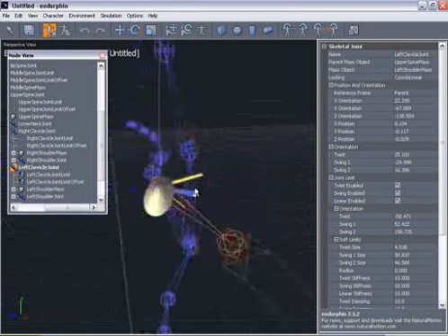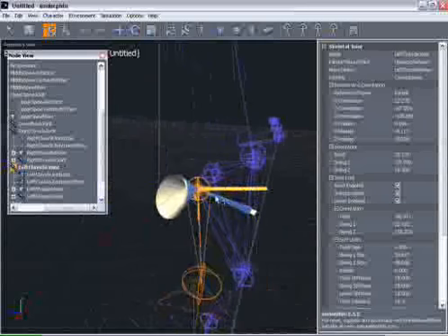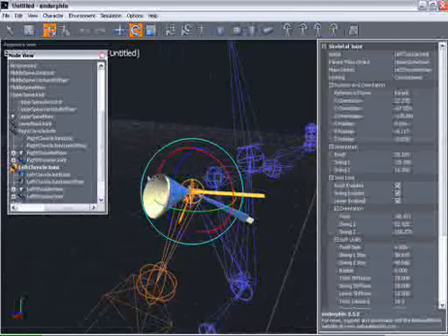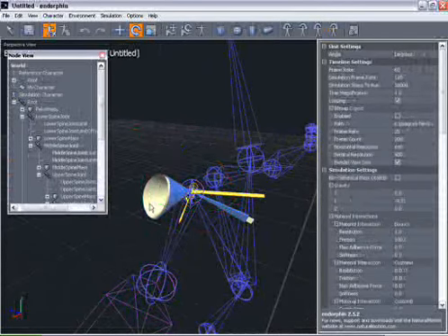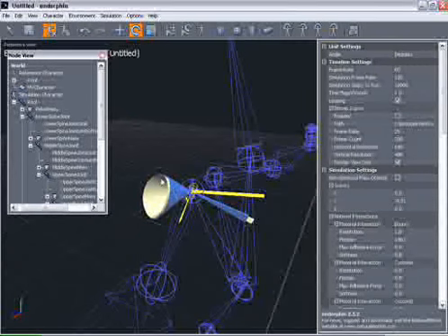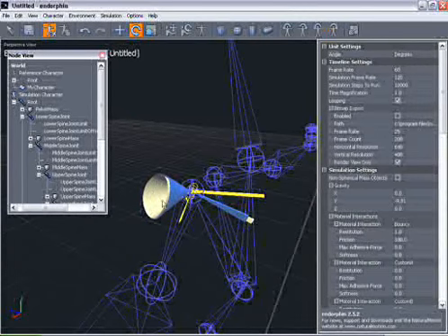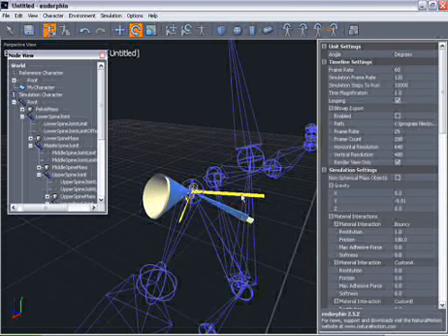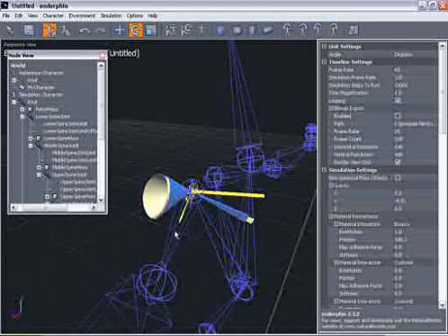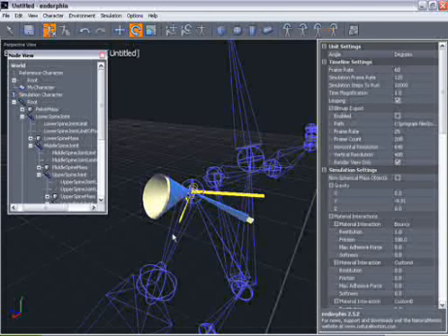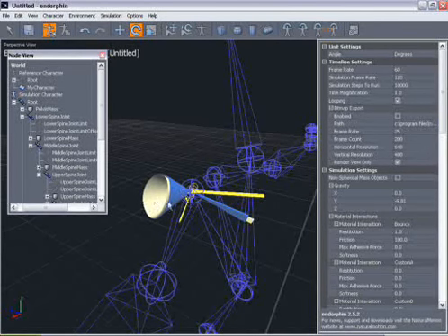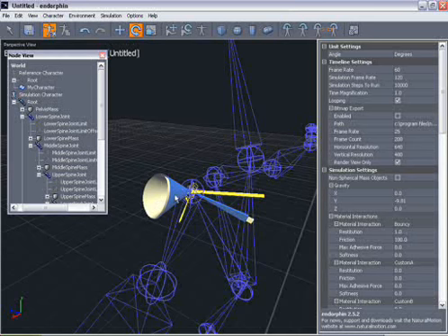So let's have a look there and see what we've got in the viewport. So we've got two parts here. We have the swing limit and the twist limit. The swing allows us to rotate the joint perpendicular to the joint anywhere within the cone, and then the twist limit allows the joint to twist along the axis of the joint. So as you can see here, this joint has got a bit out of place because we moved this inner shoulder joint so much to start with, that the cone has actually become out of place from the joint.